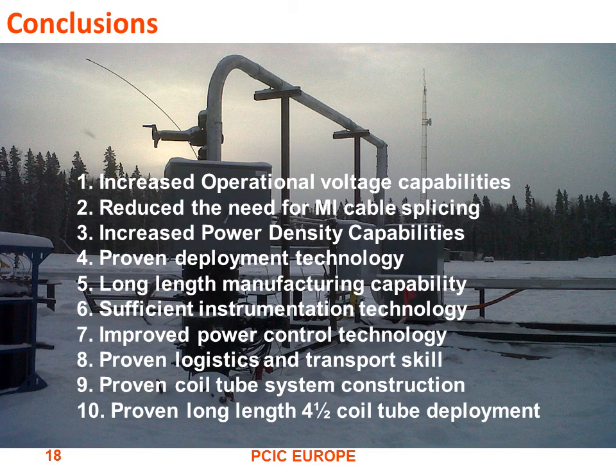We reduced the need for MI cable heating splices. A lot of the original pilot work that's been done was done very well with splices, but you can't use that in really long cables, both because of reliability and economic reasons. We increased power density capabilities where before people were talking maybe 100 to 300 watts a meter, and now we're operating at 1,000 watts a meter.